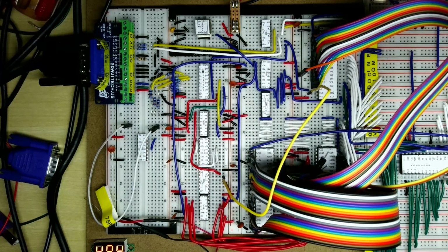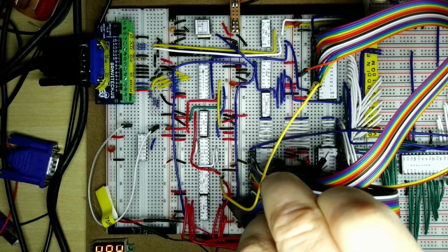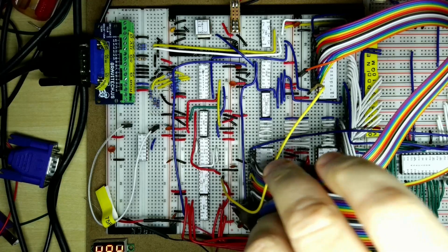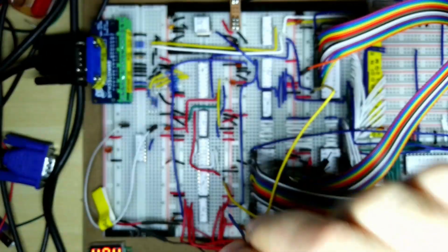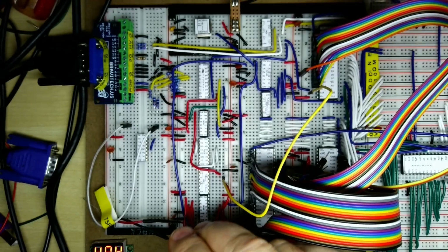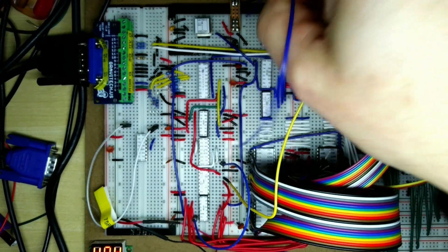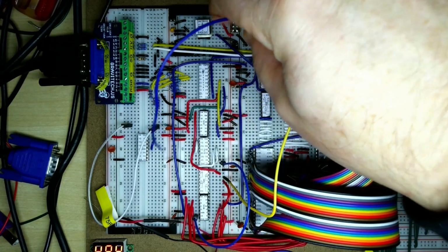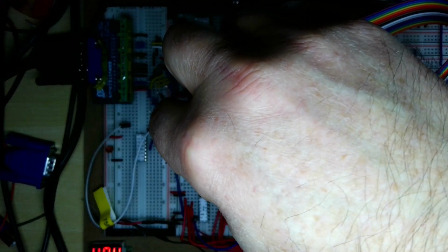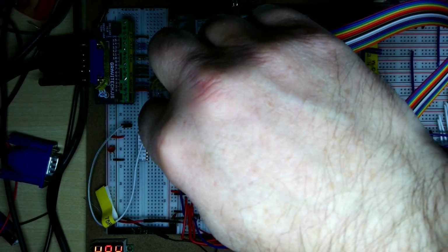What we're going to do is to temporarily unplug this signal here. So this is the current latch load signal actually coming over here, and we've actually got the dot clock down here. In fact, the output from here at the moment that we're currently taking down on this hardwired track, we're going to put this into the 1D. So this is the input of the first flip-flop.